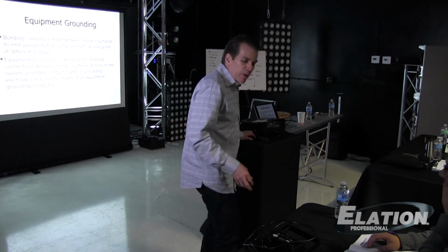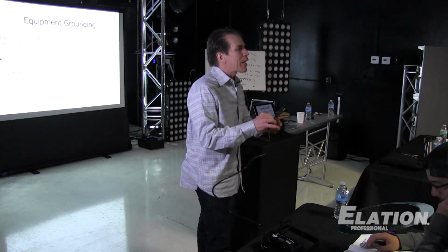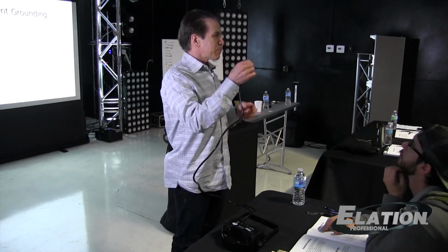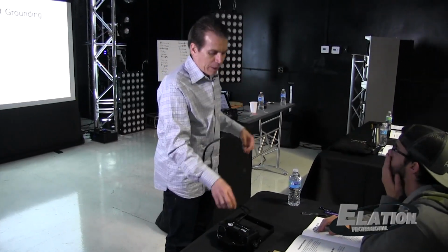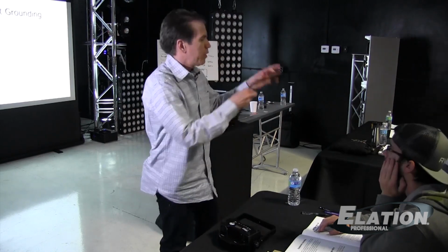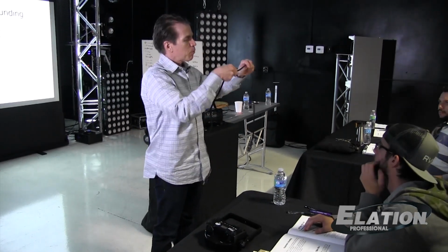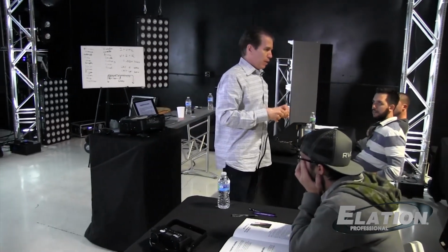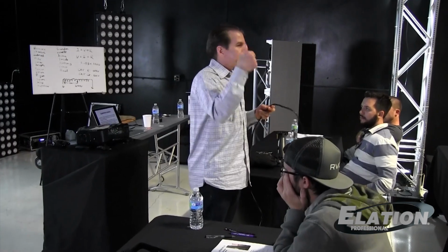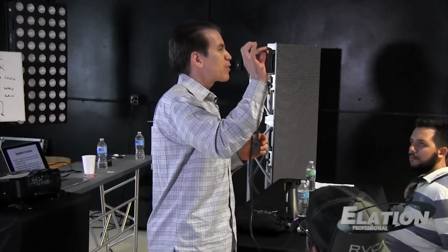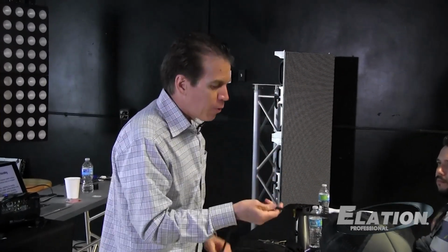And of course, you want to inspect all of your cables. Make sure nobody's cut off the grounding terminal. Make sure the cable is not broken and not compromised in any way. There's no broken wires. There's no broken insulation. I've seen this before, especially outdoors, like amusement parks, because the sun, the UV rays, will cause the jacket to get brittle and crack. And now you've got live exposed conductors. So you want to inspect there.